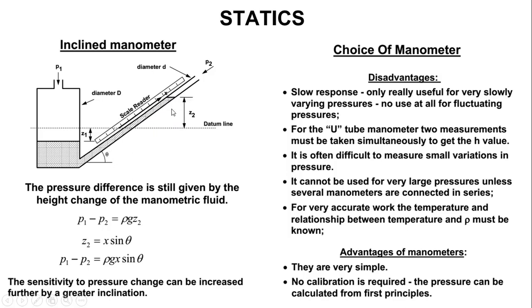So to find this side, if we work with those trigonometrical ratios, we will know that this side is X sine theta, to find the Z2. Okay. Then the rest is the same. We have to find where the pressures are equal, equate that P to that P, find the pressures, and solve what we are supposed to solve for.